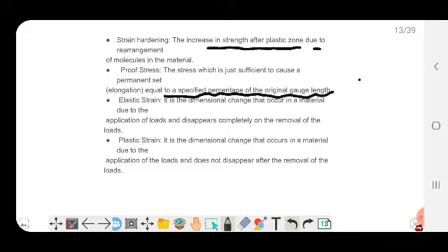Elongation: we have taken the gauge length to be 5.65 root A. Then we fixed a particular percent, that is 1% in the graph. We have already seen it is 1%. So it is the stress required to increase the length by 1%.